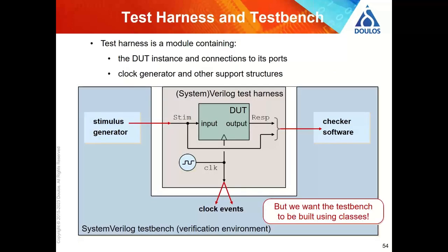Now we need a test bench. So I'm going to speed things up a bit because we've still got a few slides to get through. So with our test bench, we actually want to provide a complete environment. Okay, so we've got a stimulus generator, we've got a checker, and we're going to write that. And ideally, we'd like to make this a class because classes are much more flexible.